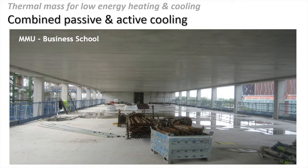And that's the finished result, really high quality finish. And they actually used a combination of 75% white cement and 25% ordinary Portland cement to produce the precast units. So it gives a really light finish. No need to paint that, and really good from a daylighting perspective as well. Cuts down on artificial lighting, which is also important.